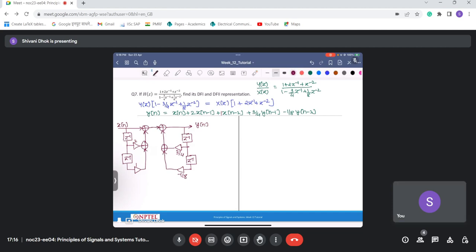Okay, great, madam. So that means first look at the numerator of H of z and start from left, and then look at the denominator and start from right and inverse. Yeah, correct, inverse. So this is my direct form 1.